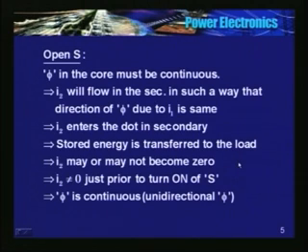After some time, I open the switch, and the stored energy is transferred to the secondary. The direction of flux should be the same. In other words, the direction of flux produced by the primary should be the same as the direction of flux produced by the secondary. So if current enters the dot in the primary, current will enter the dot in the secondary.